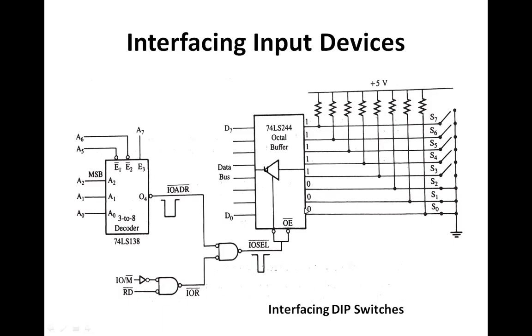So whenever the microprocessor is going to execute the IN instruction, it will first read the machine code or the hex code of the IN instruction. So the first machine cycle will be elapsed in fetching and executing the hex code of the IN instruction. And the second machine cycle will be used for fetching the port address, that is the 8-bit number. So it means 2 machine cycles will be used for fetching the instruction and executing the instruction IN 8-bit. But that is not all.